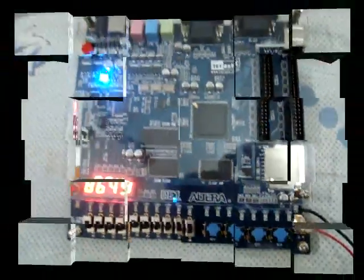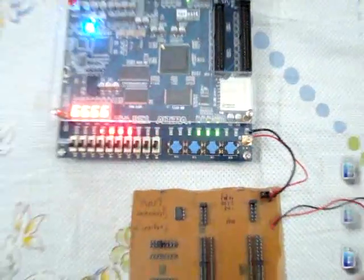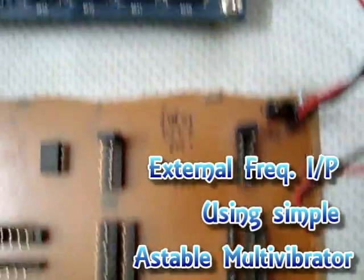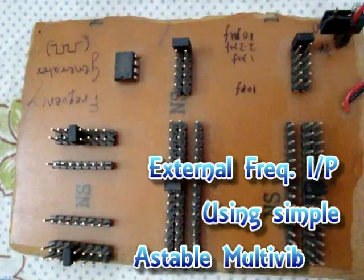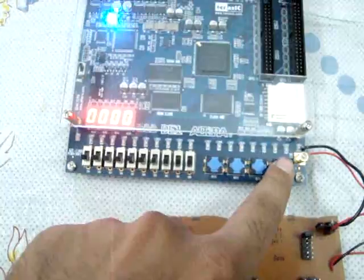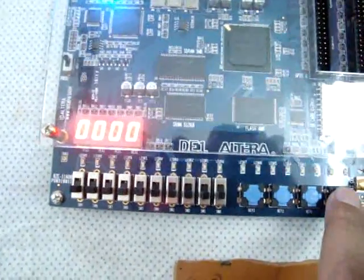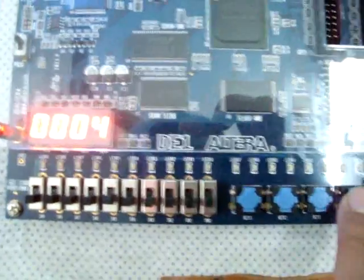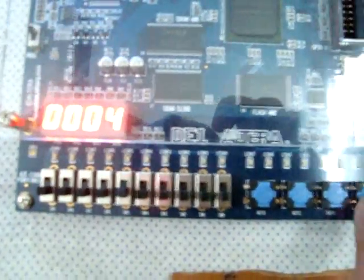Now let's measure the external signal. The board is ready now and the input frequency is given through the SMA connector on the DE1 board. The input frequency is set to 3.22 Hz now. Okay, now let's run the code. The code is on the FPGA. Let's start the process. So the 3.22 value is rounded up to 4 Hz and the frequency measurement is correct.